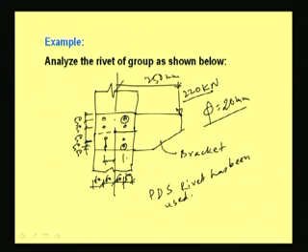Because the distance is less, Fm will become less, and in this direction rivet, the Fm will be less, because Fm will be to some extent in the opposite direction to the Fa. So, the resultant force on this rivet group will be less, because it is going to oppose. So, we will only check whether these extreme rivets are going to take this much load or not.